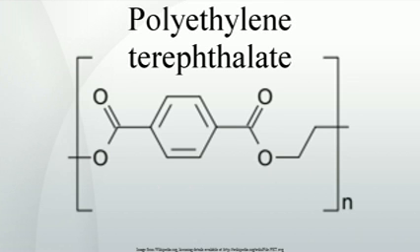Manufacture of PET pellets or flakes for bottles, bottle-to-bottle and APET. This process is, in principle, similar to the one described above. However, the pellets produced are directly, continuously or discontinuously, crystallized and then subjected to a solid-state polycondensation, SSP, in a tumbling dryer or a vertical tube reactor. During this processing step, the corresponding intrinsic viscosity of 0.80-0.85 dl/g is rebuilt again and, at the same time, the acetaldehyde content is reduced to less than 1 ppm.